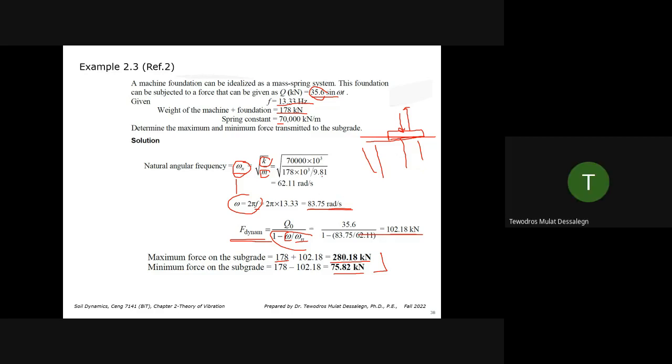Anybody has any question? This is a very important concept. Resonance, the concept of resonance. Try to avoid the two natural frequencies being close to each other. They cannot be the same. Some motors work at a larger frequency or at a lower frequency, but they cannot work continuously around the natural frequency of the system, because you'll have excessively large force and at some point it fails.